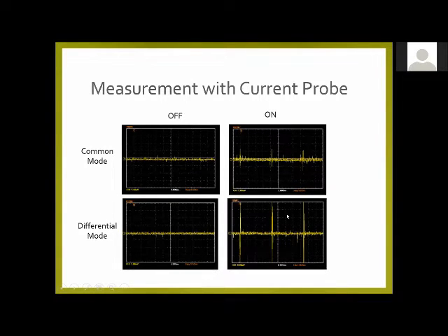If you then separate the wires and clamp the current probe only on one of the wires, you'll get differential mode current. That's current that comes through the one wire and back on the other one. Since it's the way the system works, the light bulb is lit up, you actually have a lot more current in differential mode than you would get in common mode.